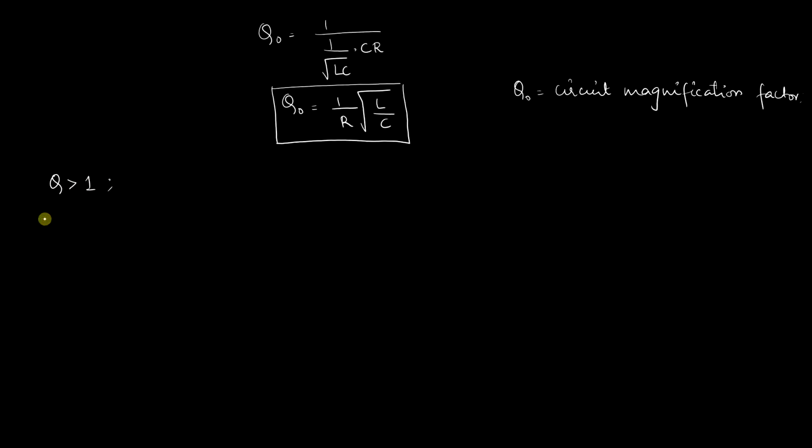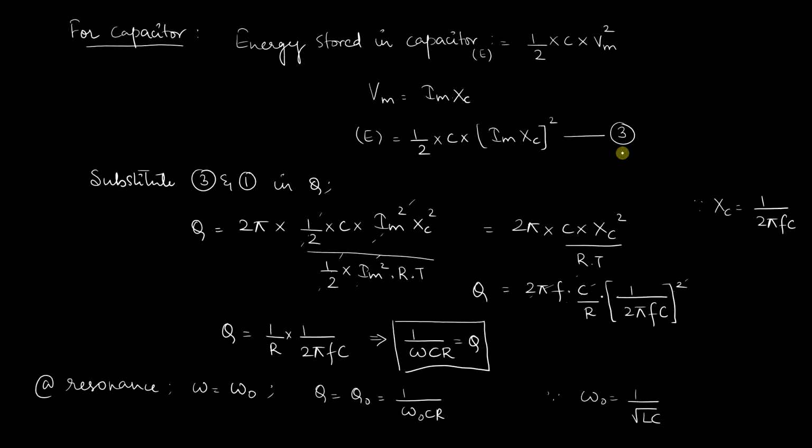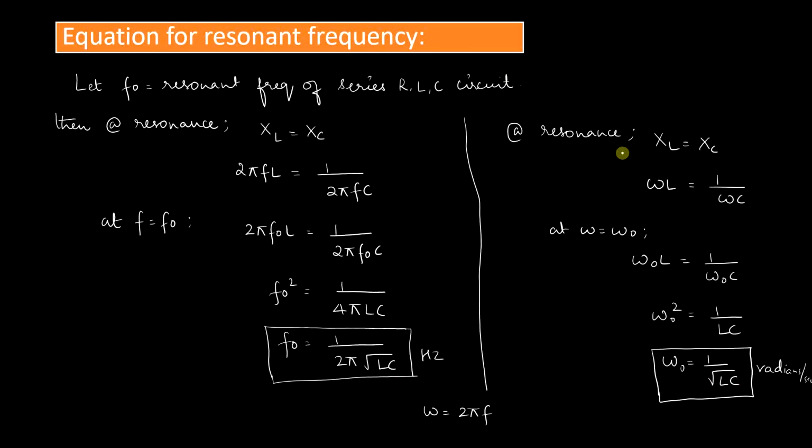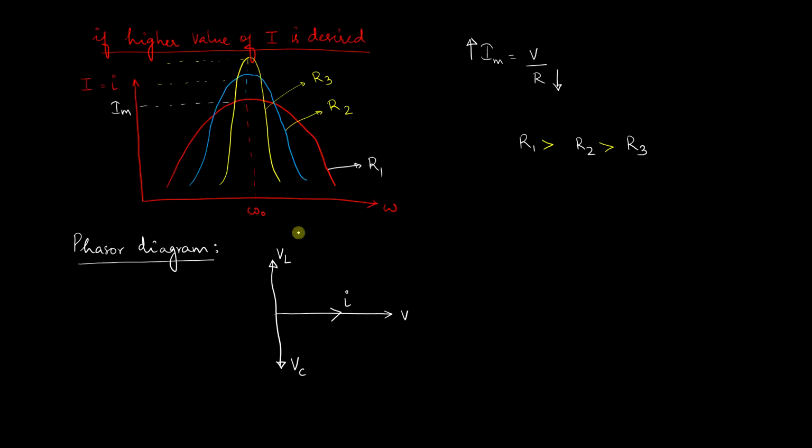Now what is this quality factor? We have derived and defined it mathematically, but why do we need to compute this? So quality factor basically gives us the sharpness of the resonance curve. If you observe, I have a graph here with different frequency responses drawn. If I have a very high quality factor, that means I will have a response curve something like this, shown in yellow color.